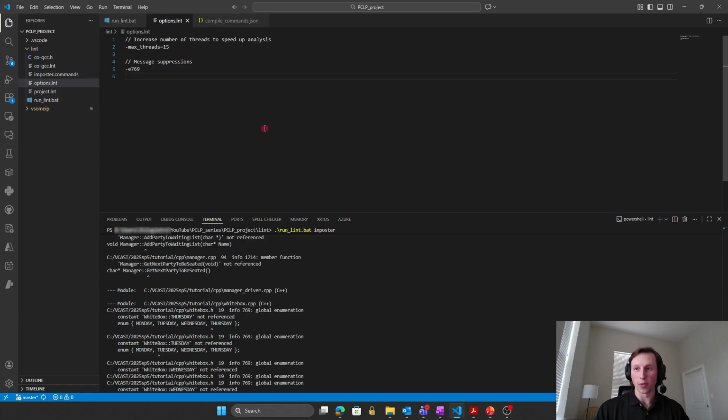So there are multiple different ways that we can do this, and I can't stress that enough. There's more ways than I can go over in one video to suppress messages from PC-lint Plus. The key part that I want to point out is that each PC-lint message comes with a certain code number. And I would say that this is the primary way that you can easily suppress a message from your PC-lint output. So we have this terminal output here from running the analysis using our script.